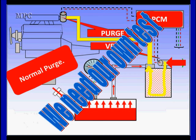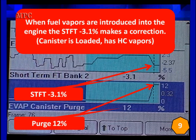We can do our own test. We will do it, not depend on the PCM. Here is a test. We're driving down the road. Now I want you to look at several things first. Notice that short term on the left is moving around quite a bit. What we're going to do is wait for very specific things. Look at purge. It was at 0%. Then at the dotted line, it goes to 12%. Notice short-term fuel trim. It was up about plus 2.3, and the same moment we changed this, it dropped to minus 3.1. That's about a 5% change.